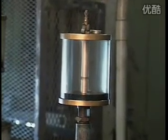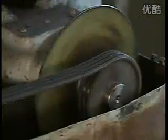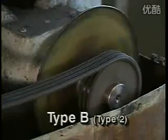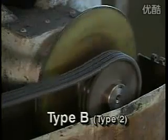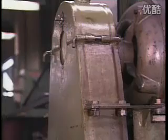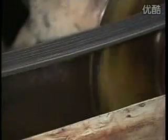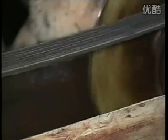If the conditions are not severe, and the chain drive is not accessible, then a drip-type reservoir can be utilized to apply small amounts to the chain. The second lubrication method is Type B, or Type 2 lubrication, involving a bath or disc. The bath method employs a case which holds lubricant and allows sections of the chain to run submerged in the oil every revolution of the drive. The disc method applies oil to the chain as it rubs against a disc, brush, or other implement.